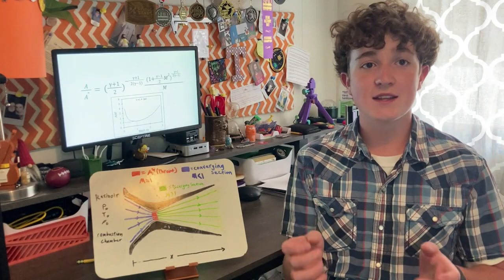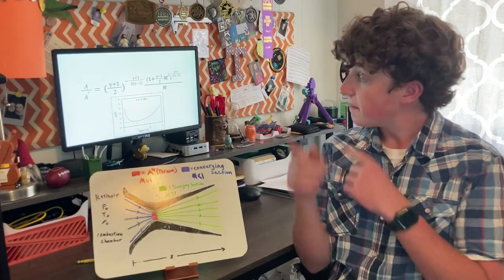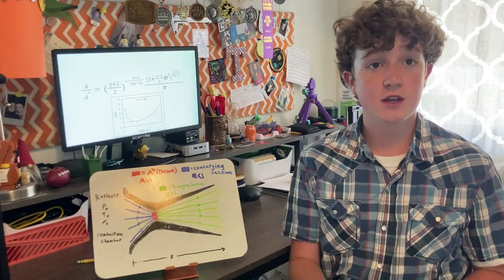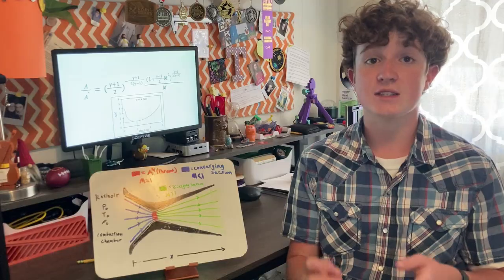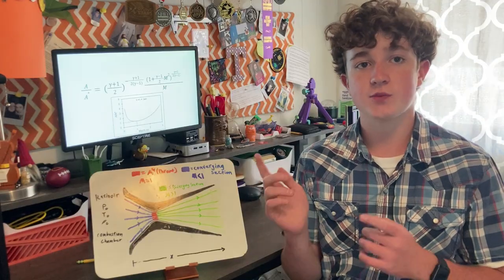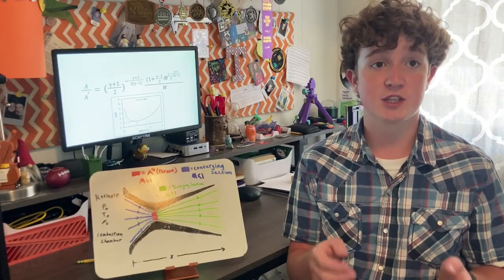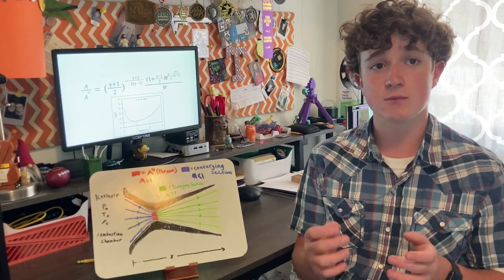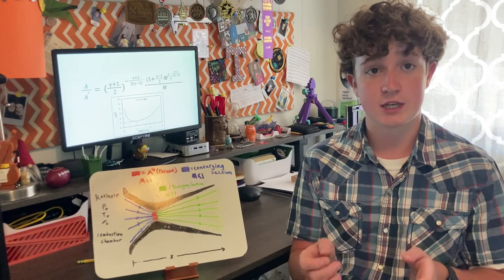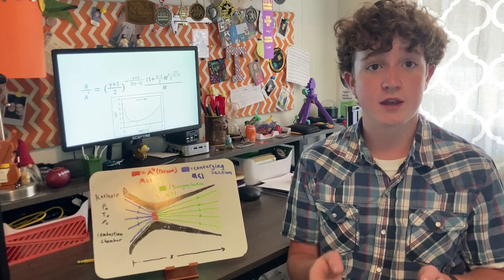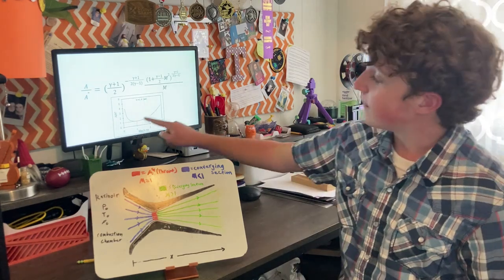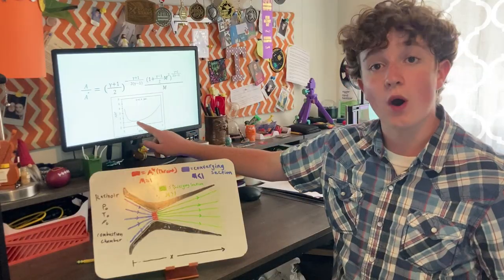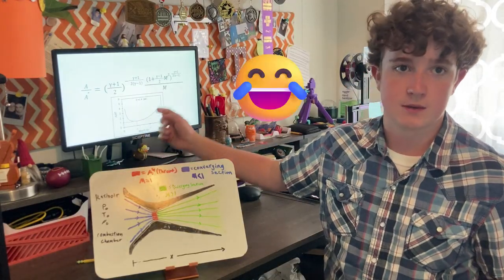Next up, we are analyzing the area change in the nozzle. This equation relates the area along the nozzle to the throat area, based on the Mach number. This graph shows what happens to the area ratio as the combustion gases continue to accelerate. What we see is that as we start to get past Mach 1 and into supersonic regimes, the ratio of the area to the throat increases, given by this spike here. It is equal to 1 at the throat, obviously.